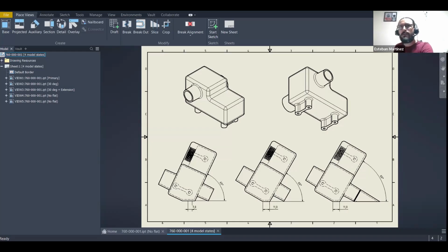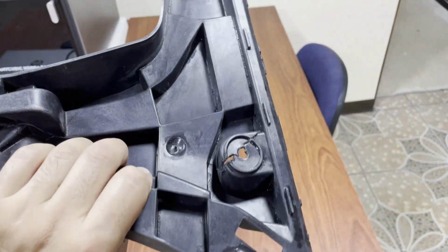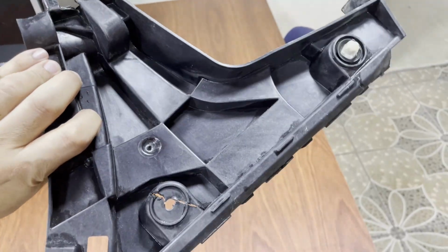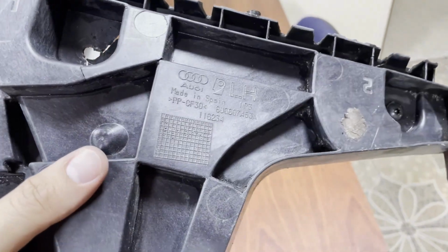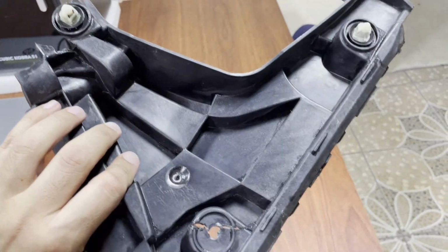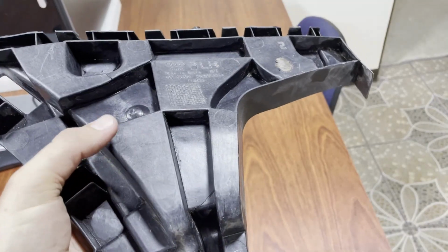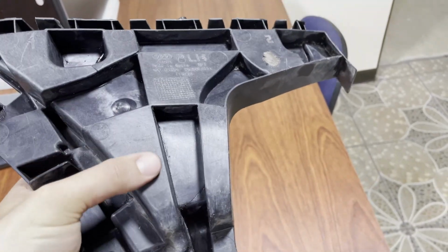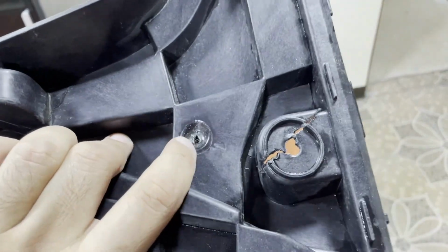If we take a plastic part as it is coming from the mold and we put it on a 3D printer, we're going to potentially see a lot of overhangs, for example, when we don't have an even surface where to put the part for 3D printing, which is going to mean that you need a lot of supports and maybe painful reprocessing, right? So overhangs is the number one.